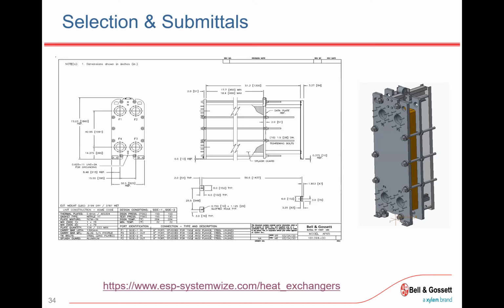You could essentially pick these by saying everything from pump speed. I want to have a lower RPM, which aligns typically, at least according to the DOE, the higher the RPM, usually the lower the lifespan. You could say I want a base mounted unit, but I want a small footprint. Base mounted units versus inline units typically last longer. All these different things to filter out, or you'd say these are the ones I choose.